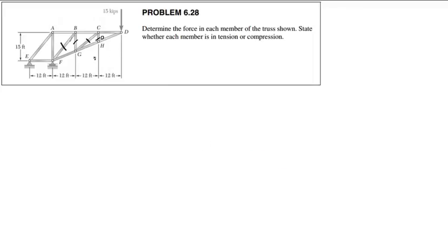But look at this. By bracing this here, I have reduced the effective length of the column to 1/3 of its previous length. What that means is simply by adding these bracing members, even if I don't need them to carry any load whatsoever, I have now increased the compressive capacity of this column by a factor of 9.